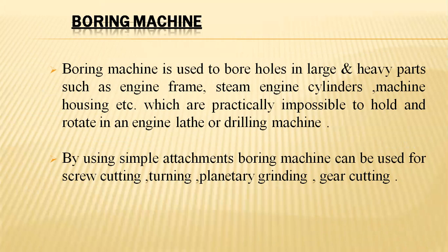Normally we use such heavy objects in engine parts, automobile engine parts, such as the basic frame of the engine, steam engine cylinders, and even machine housings, frame structures of entire automobiles, casting objects, mounting devices, etc. Parts which are practically impossible to hold and rotate in an engine lathe or drilling machine can be accessed on this boring machine.